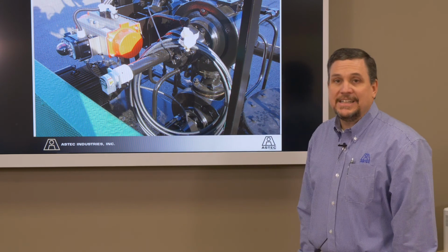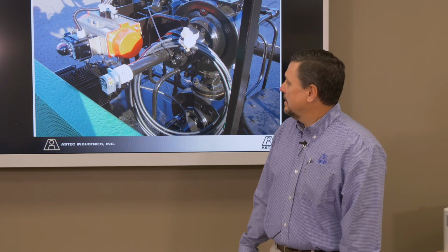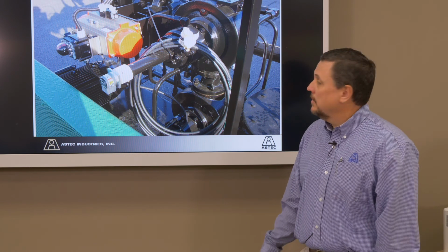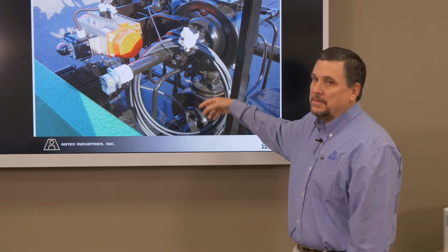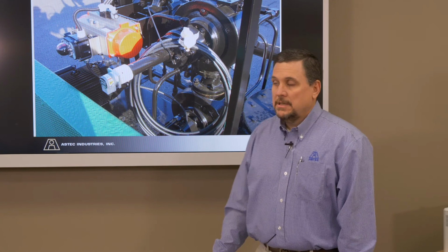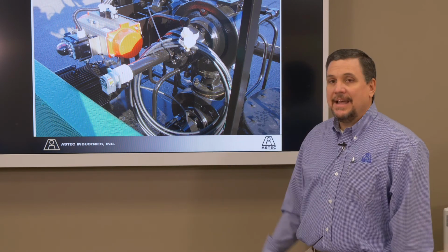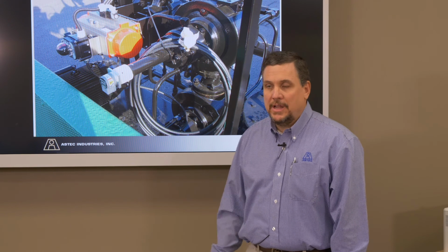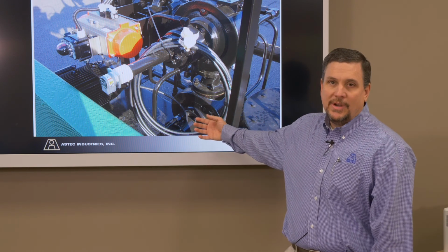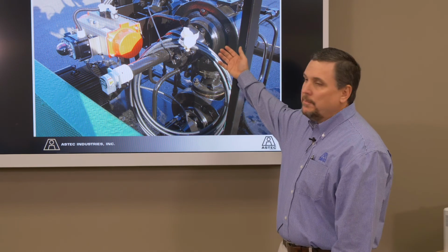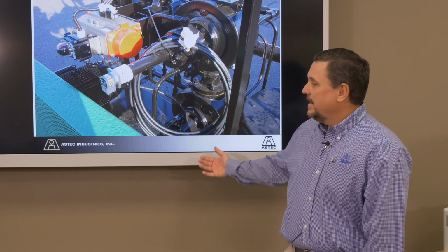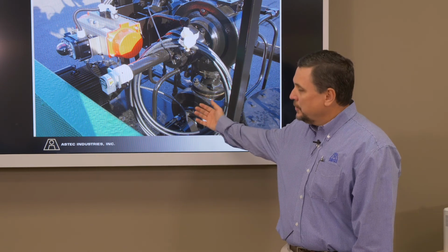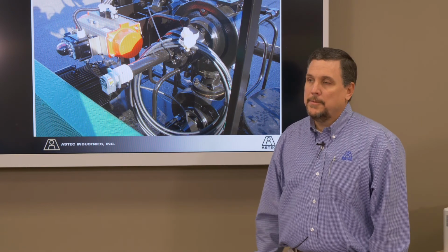So we're getting that tach signal or that encoder signal back into the control room for the process control to make mix. The main difference with the pushing pump is that these two pumps are going to be the same pump. They have a plate on the back side that allows one to have a bypass on it. Your pushing pump will always have the bypass. Your metering pump will not. It'll have a blank flange on the back of it. So that's one way to tell. Also, your pushing pump's always going to be the one hooked to the motor.